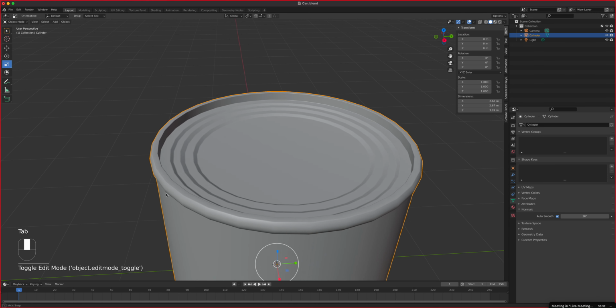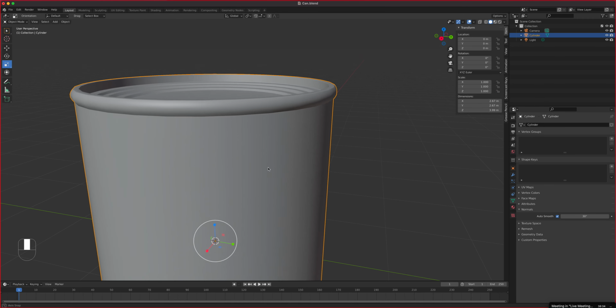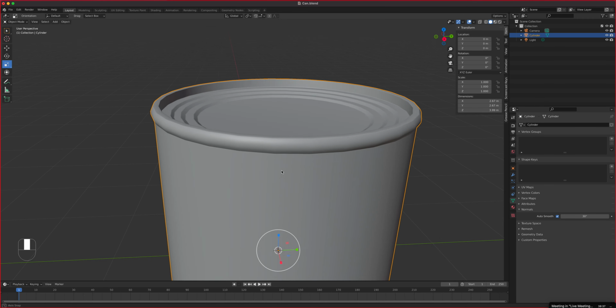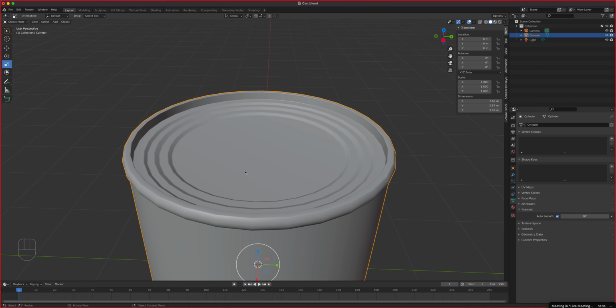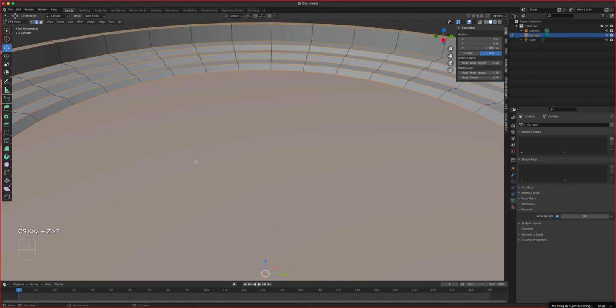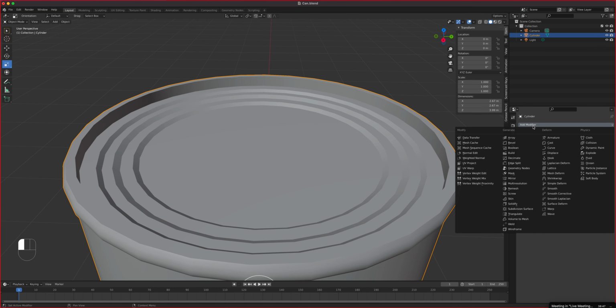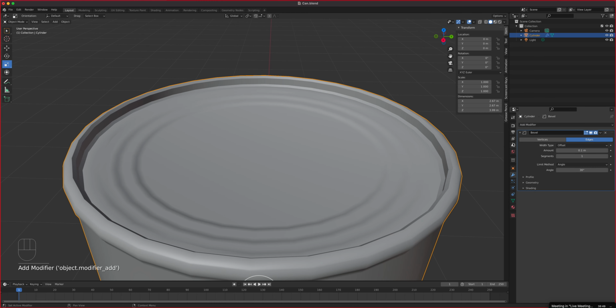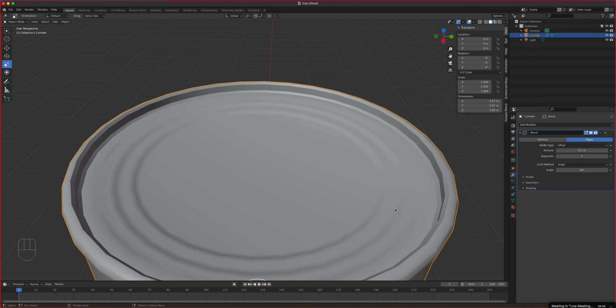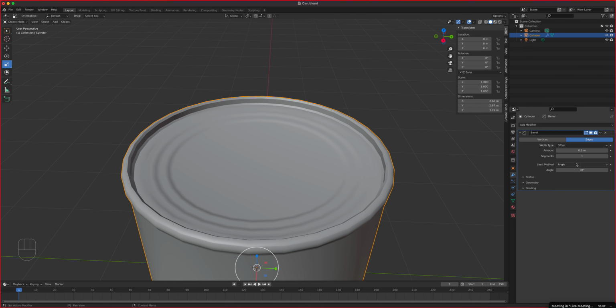All right, so that gives that softer look. Did it add too much geometry? Maybe it did. So let me click undo on that one. Before we try that, let me just add a modifier here called bevel. What it does, it adds kind of like a fake bevel. It probably did too much on this one because our can definitely went a lot smoother here. So I will lessen the amount. I'm going to hold down shift and drag this down so it goes into tiny numbers.